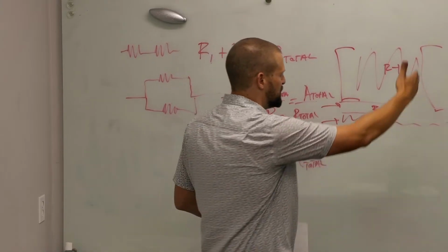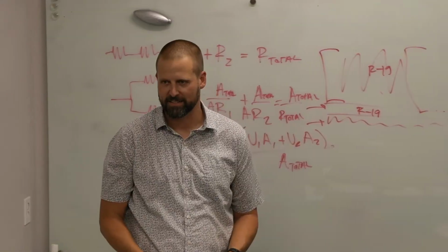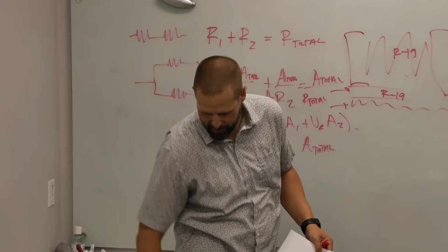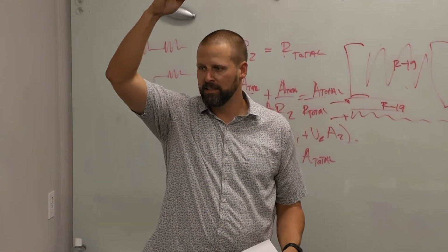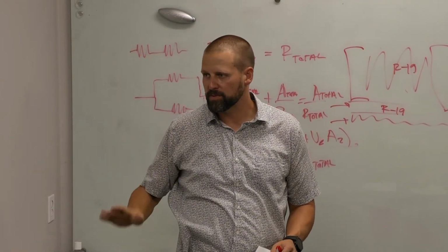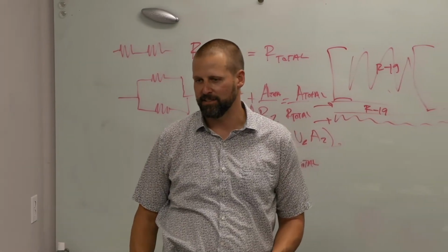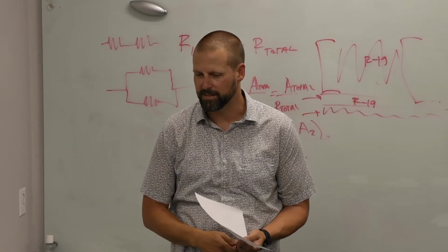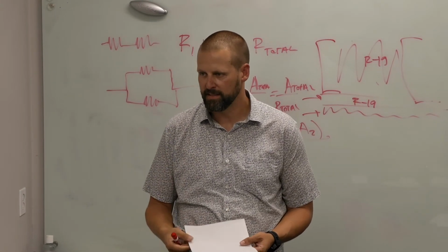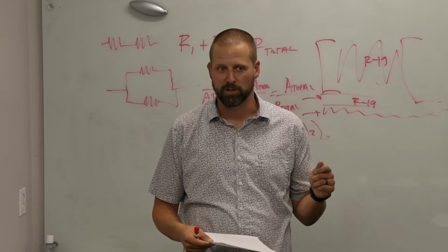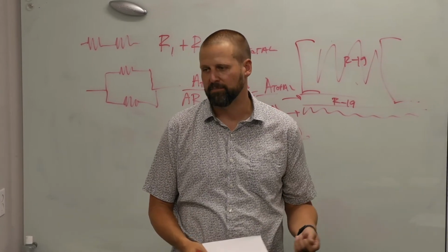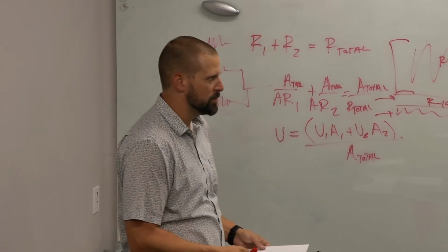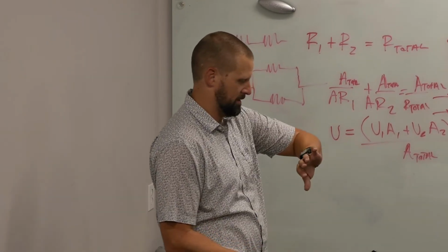So it's a continuous piece of glass, and we'll build up insulation in walls below a certain height and above a certain height. There's a lot of complicated calculations you can do to calculate that assembly, and we've used that on some of the high rises we've done in Culver City to be more aggressive with our assembly type and meet code. Which is going to be my segue to windows, I think.